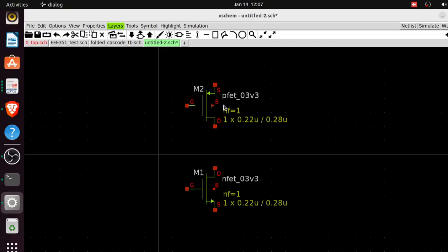Yeah, so I would have my power supply, my VDD up here, then my ground down here, then my output in between. Remember, that's how a CMOS inverter is. Then I would connect the two gates together. So that's what I'm going to do now.